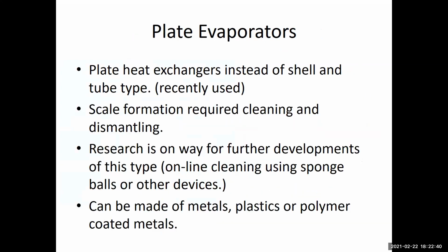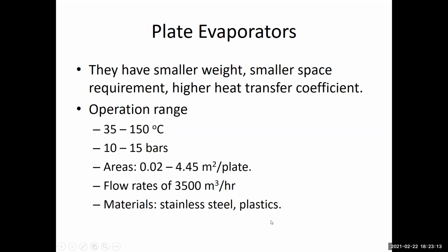This is the definition I was just talking about here, and the latest technology is coming with the plate heat exchangers that are going to be used, but again, having to be careful with scale formation because you are losing a large number of plates and the plates are packed close to each other. So there is a problem associated with cleaning these units: you should dismantle the unit, take it for cleaning, and then put it together again. But the heat transfer coefficient is high, and you can use new materials which are recently developed for operation of these systems.